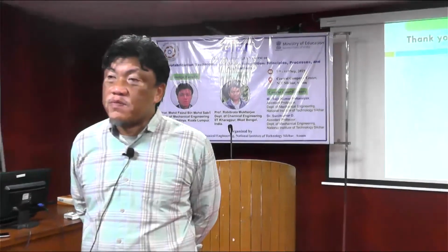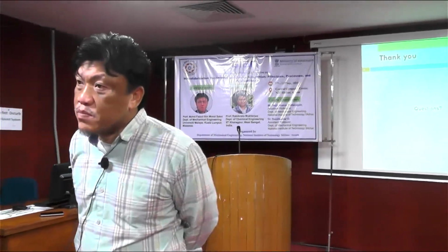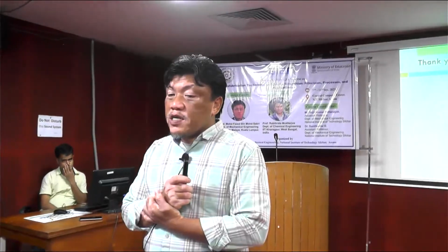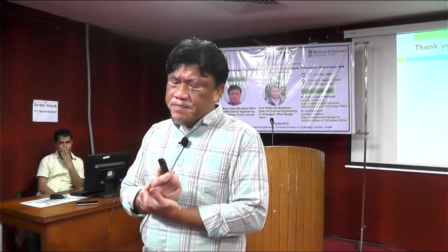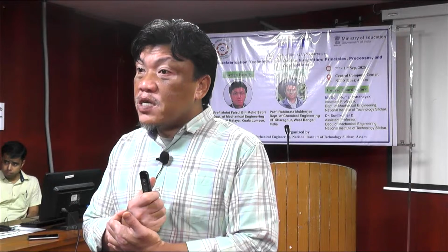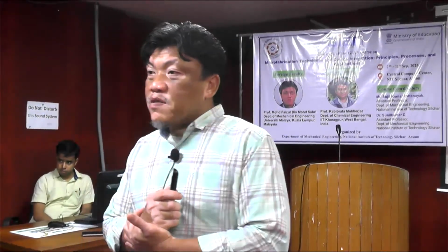Sir, hello sir. How can we easily control the etching depth? Etching depth is controlled by time. If you talk about wet etching, it is time and also the concentration of the chemical. The main parameter is time, time dependent. Okay sir. Thanks.